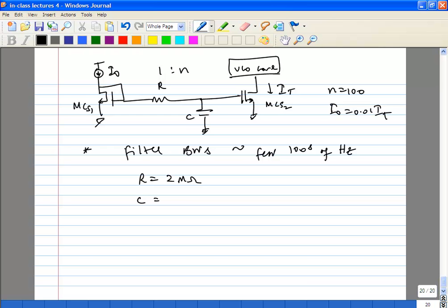Yeah, we are going to look at it. Of course, we'll take a look at it. Unfortunately, you don't have a choice, because you are more worried about noise than area at this point, and it's still better than going with a different architecture which may require 2 inductors. Quite often, a lot of journal papers or conference papers show you the layout. If you look at the layout, obviously the number one thing you can see is the inductor of the VCO. Surrounding it, you will see a lot of these big yellow squares which may look like they don't mean anything. They are typically the capacitors, the bias filter capacitors. That's very common.